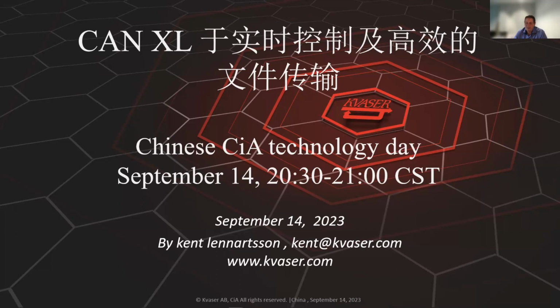So I have mentioned in my talk, there is a new working group, large network topologies, starting with CAN-FD, but also having CAN-XL in mind. When we're talking about bitrate and how much we can achieve, as Kent already touched on, we always have to keep in mind which kind of topology we have.